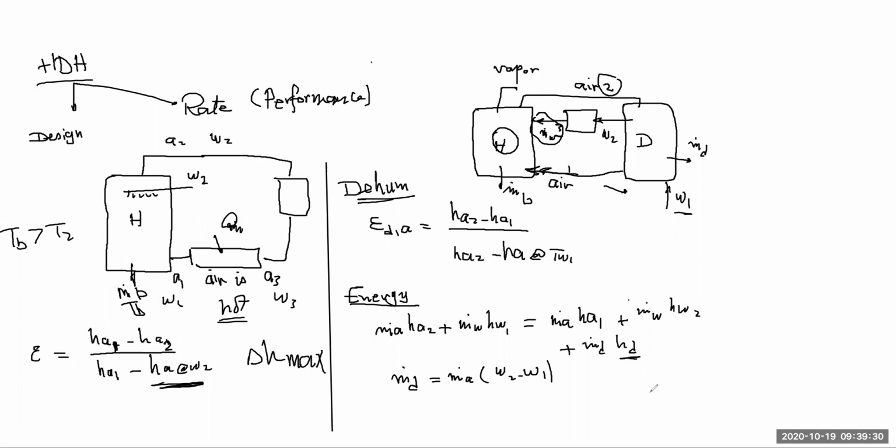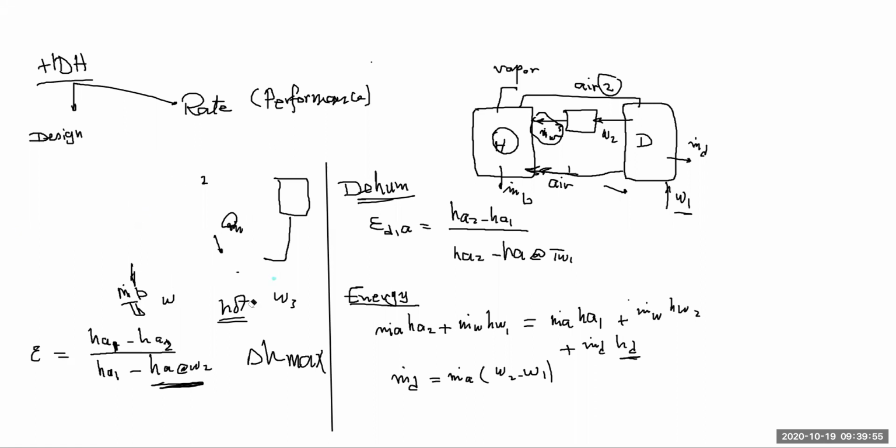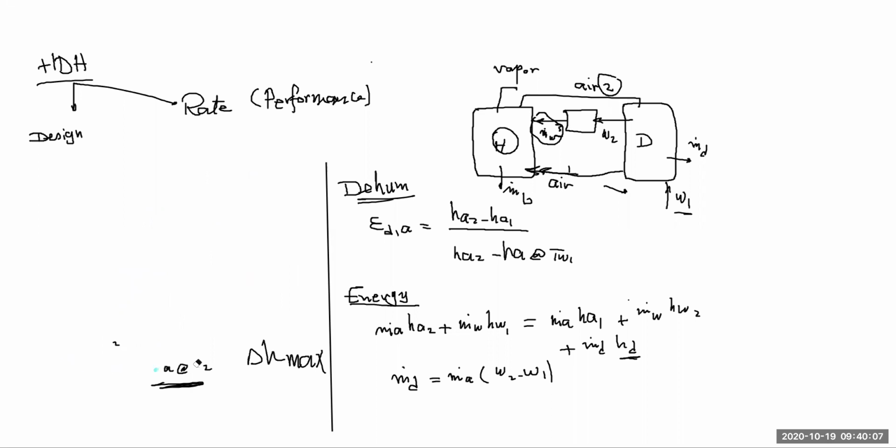The only difference that I did not talk about is in case we have air heating after it leaves the humidifier, which is the modified air heating cycle. And for this cycle, there is some difference here, a piece of information that we don't give to you because we assume that you should know it. And that normally becomes, in some cases, the trick of the problem, which is the kind of heating that happens in an air heater is sensible heating. The example that we have solved in class was of that kind.